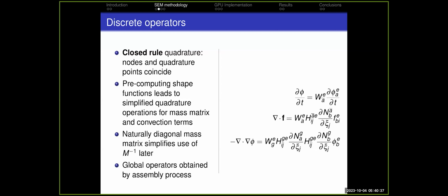For example, on the divergence of F, instead of having a sum over all of the Gauss points for every node of the element, we essentially just fill each node. Remembering that a hexahedron element of order P8, for example, can have 729 nodes and 729 Gauss points, this is actually rather essential for us.